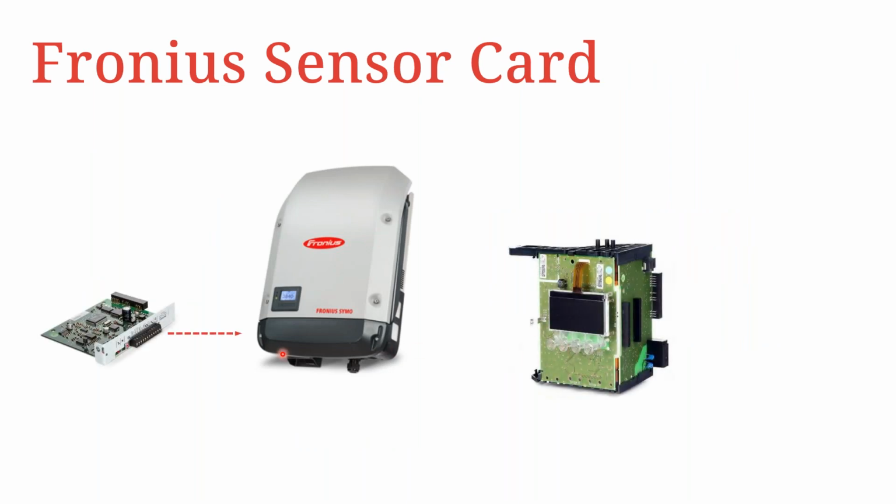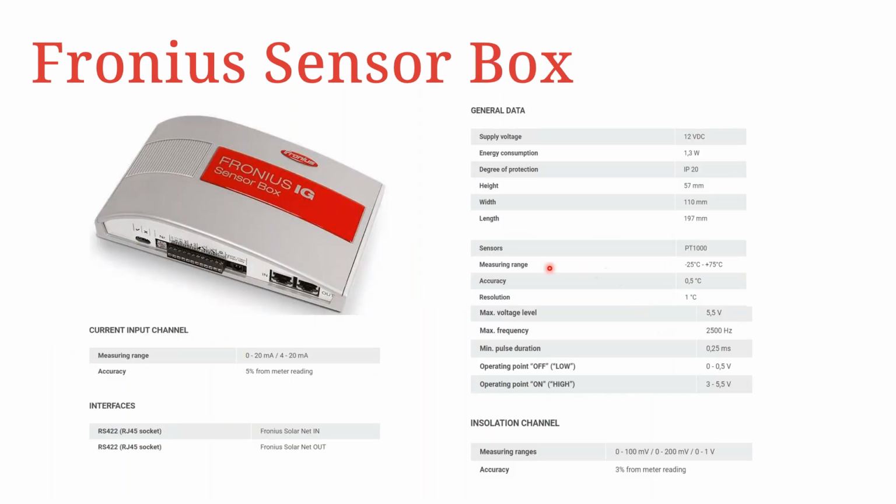As mentioned before, when you want to integrate the sensor card into the Fronius inverter, you are going to integrate it into the same area that accommodates the data manager cards. Here, this is the part of the inverter with the display, and this is what we refer to as the reservoir of the inverter. You can see the LCD here, and once you open up the inverter front cover, you're able to access the slots where you can integrate or retrofit the sensor card. You can take any of these two slots for integration of the sensor card.